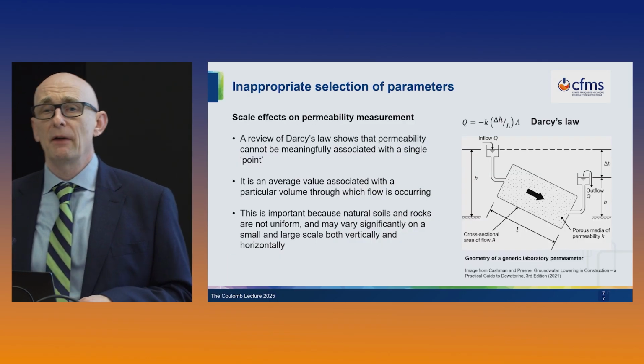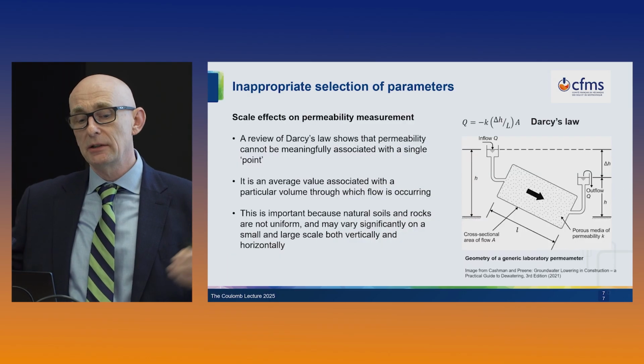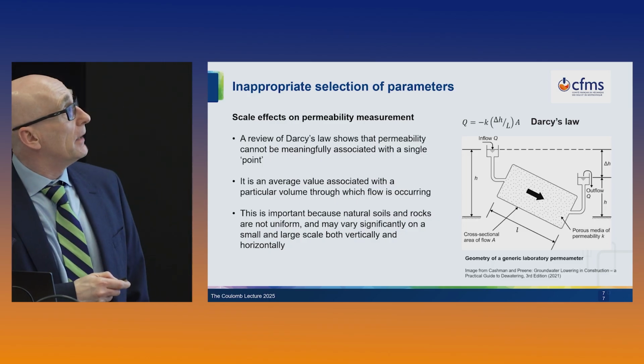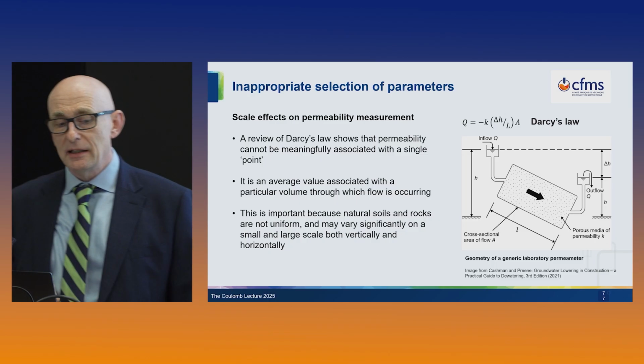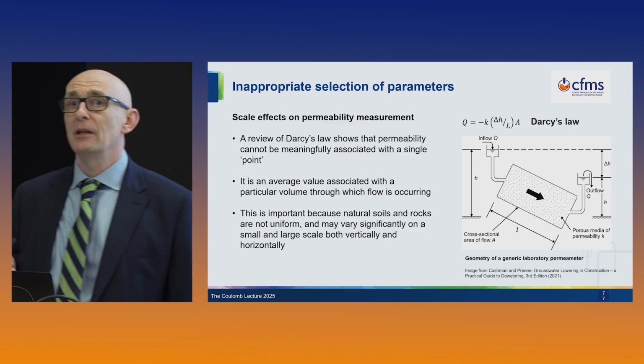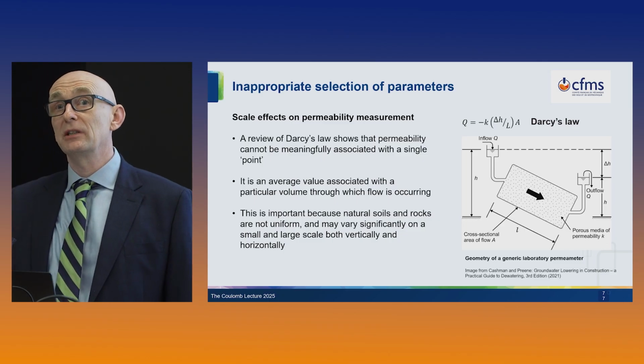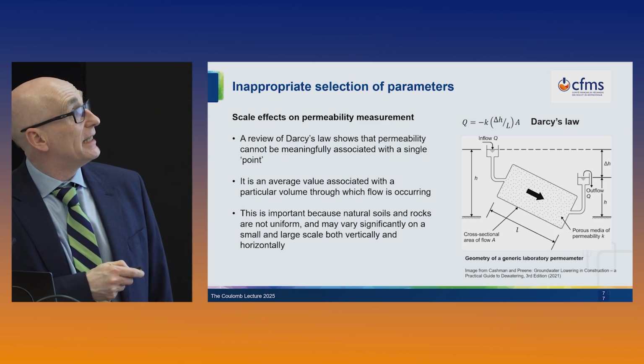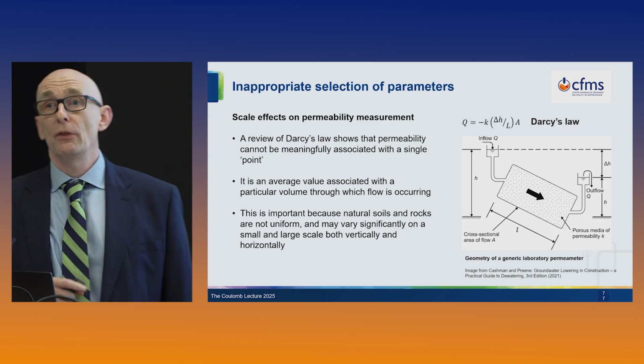And I want to talk about the effect of scale, the effect of size on permeability measurement. So we have Darcy's law, and the point to realise is that Darcy's law shows that permeability cannot be meaningfully associated with a single point. It has to be associated with a volume, because Darcy's law contains an area term and a length term.